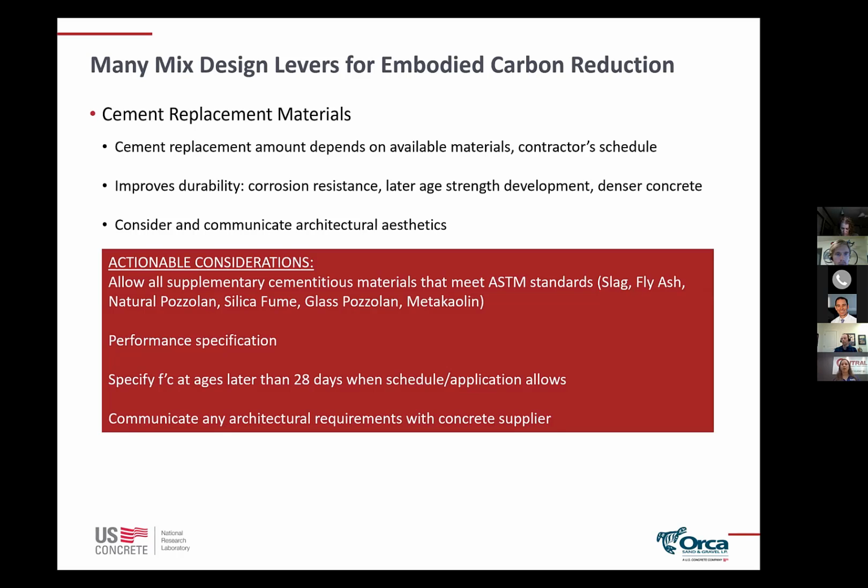Something to consider as well is to specify your design compressive strength at ages later than 28 days when the schedule allows or the application is appropriate. And then again, making sure to communicate any architectural requirements with the concrete supplier is important.